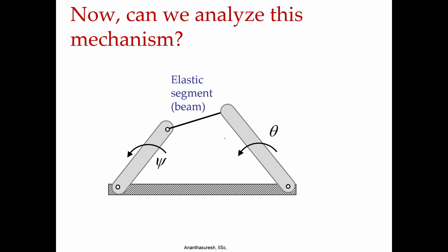And what about this? Now, I had put this in the middle like a coupler link, again I put a pin here, meaning the movement will be absent. So, we can deal with this because it is fixed and force can come in any direction. This also can be analyzed by putting a rigid body over here, because I am moving based on that gamma factor, and put a joint there and extend this body like this. So, this one now gets extended, right. So, then we have a regular 4 bar linkage with a torsion spring, and we can analyze it.